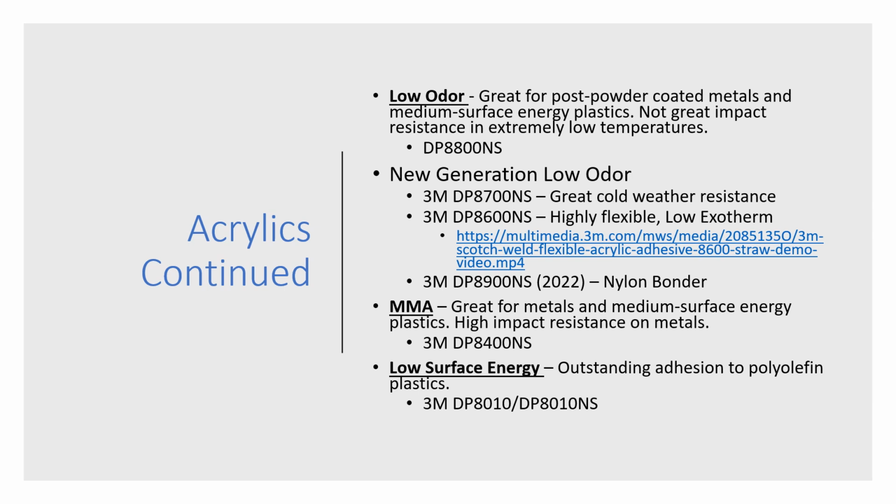3M has MMA, methyl methacrylate acrylic adhesives. MMAs are typically very common acrylic adhesives. So Lord has MMAs, Loctite has MMAs, Plexus has MMAs, Sikafast is an MMA. We also sell that. Very common type of acrylic adhesive. They're really great because they're versatile, but they have very high odor and they're flammable.